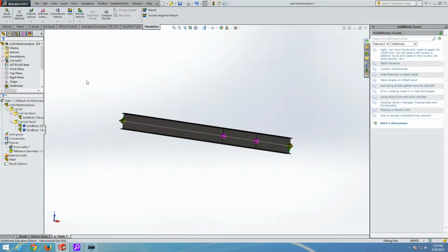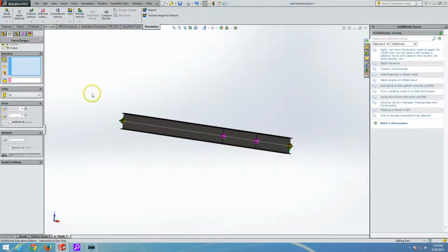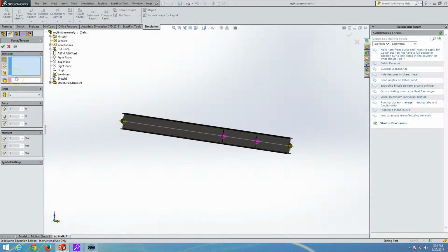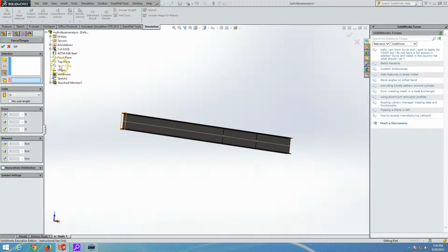Now what is the next step? The next step is to set up the external loads. To set up external loads, we go again to external loads. We have a pressure and a force, and in this case it is a force because we are looking at the linear system. Let's first set up the new one. We will click on a beam. This time we are not looking at the nodal force, we are looking at the beam force. Reference geometry is from top.